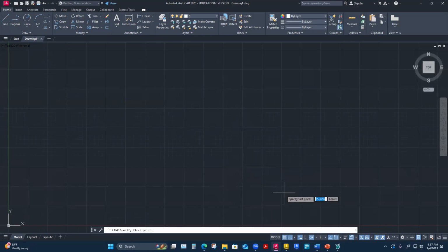The next one over that I have turned off currently is ortho mode. Ortho mode, if I turn it on, will actually keep me orthographically aligned. We've said the word orthographic projection a lot, but that is really drawing at right angles to each other. Like the front view is directly lined up with the top view in orthographic projection. They're totally in line with each other, and then the right side view is just off to the right, but everything aligns. So ortho mode is keeping things at right angles to each other. It's a way to lock your cursor in and only draw either horizontally or vertically. That's ortho mode.